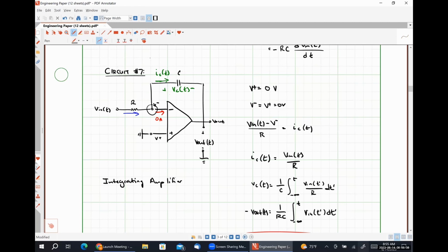One way that we could physically force this to happen, and this is how it's done practically, is we would usually put a resistor in parallel with the capacitor to give our capacitor a fixed discharge path and ensure that it has no stored energy at the beginning of our cycle.